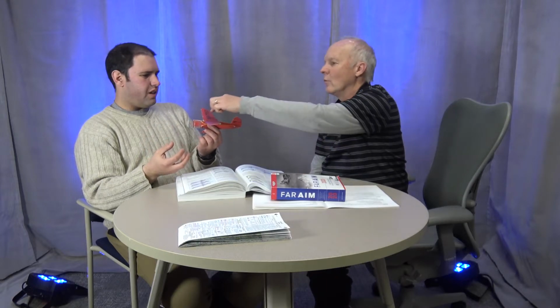So it cancels out a certain amount of lift from the wing. So the more the tail is pushing down, the less efficient the airplane becomes. But the less the tail is pushing down, the more unstable the airplane becomes. So when you're designing an airplane, you have to achieve sort of a balance between stability on the one hand and efficiency on the other. About between a quarter and a third of the way back on the wing is where your center of gravity wants to be, right?